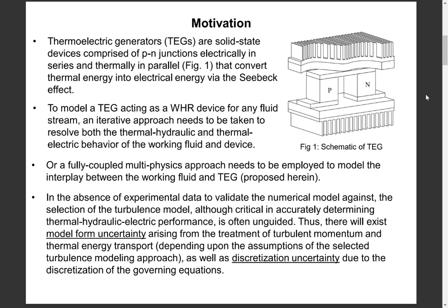When applying TEGs to waste heat recovery, to properly model the behavior, two approaches can be taken. One is an iterative approach to resolve the thermal hydraulic behavior of the waste stream, and using the set information to provide bounds to the TEG to resolve the thermoelectric behavior of the device. This arises from the fact the thermal hydraulic behavior of the fluid is dependent upon the thermoelectric behavior of the TEG, and vice versa. The second is creating a fully coupled multiphysics model, where the behavior of the waste heat stream and TEG are simultaneously resolved, which is proposed herein.